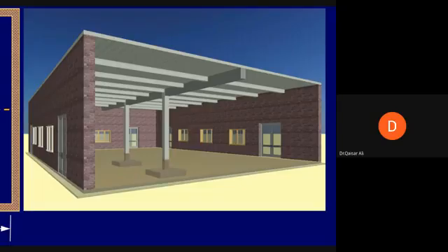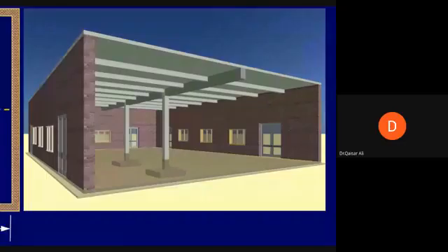If you want to draw the section of a girder, the girder is supported on one side on a wall. The wall can be treated as a hinge or roller support. On the other side also it is a hinge or roller, and at two intermediate points it is supported on columns. If you want to draw a section of a beam, the beam is supported on one side on a wall, on the other side on a wall, and at midspan either on a girder or on a column.